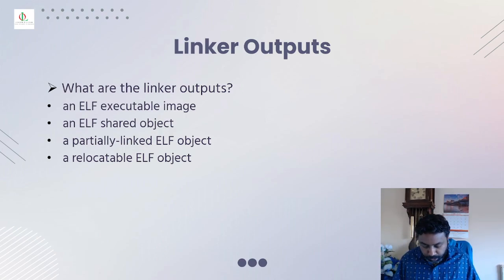That's the linker's job. By default, STM generates its own linker files, which I will show you as we move along. After you go through this, you will be able to write your own linker scripts, and it's even easier to do it that way.